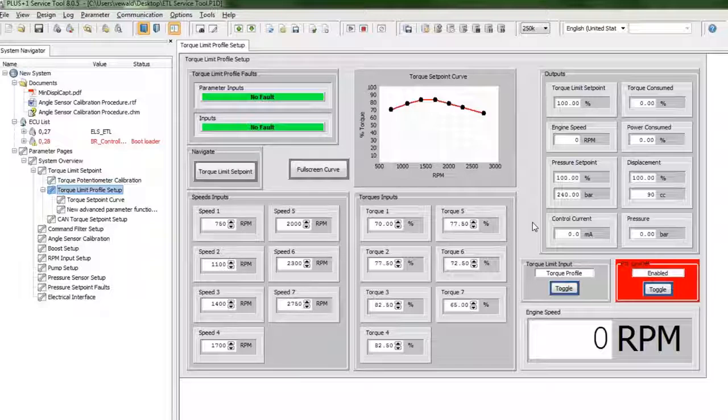For details on performing this calculation for pump torque set points, see the ETL Control User Manual. If you don't have the engine manufacturer's chart information available, start by entering the maximum torque consumable by the S45 pump. You'll then need to reduce the torque percentage allowed by a guess and check method while operating the machine to test performance throughout the engine's speed range.